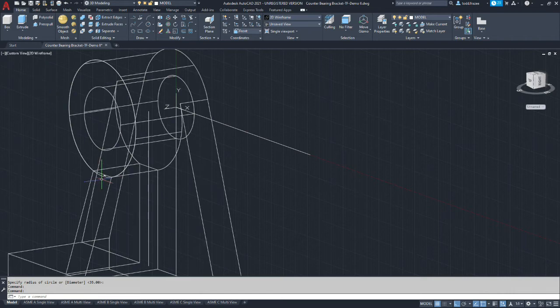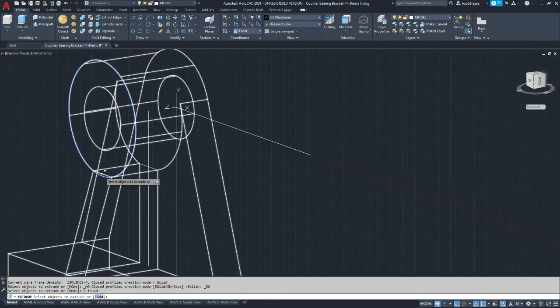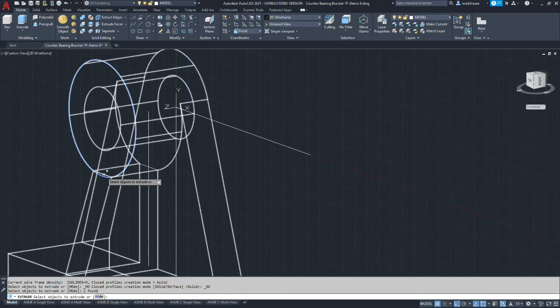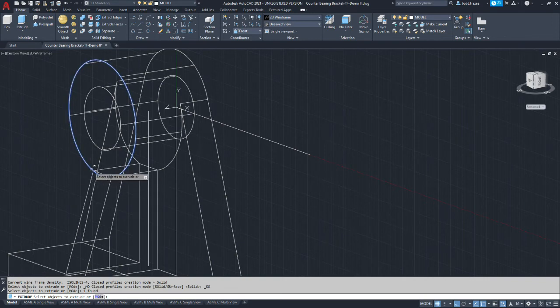Again, we don't have to create a region off the circle we just generated. We're going to do an extrude, and we're going to create a cylindrical body, and then we'll use that to remove this little piece of material here. I guess you could make just a little wedge shape and just cut that one little region, make it its own region, but I feel it's easier to do it this way. And you get the diameter where it should be.